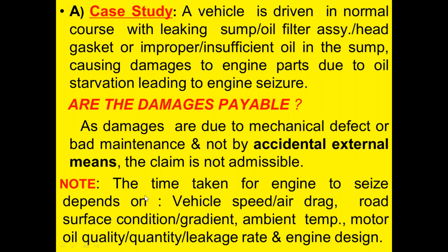Please note the time taken for engine to seize depends on vehicle speed, vehicle drag, air drag, road surface condition, road gradient, ambient temperature, motor oil quality, quantity, leakage rate, and engine design. So many factors decide the time taken for engine to seize.